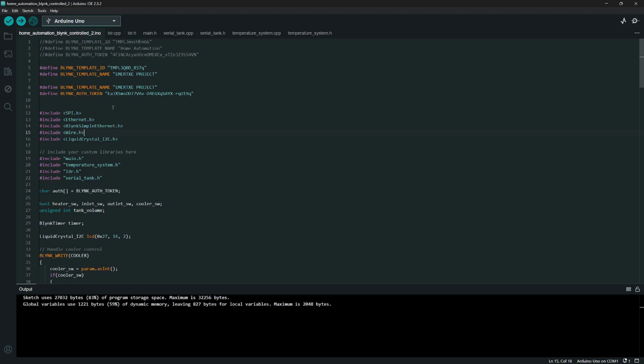Now, when we press a button, how will the sensor, or the lights as well as the inlet valves, know that we have pressed the button and wish the command to be executed? For this, we'll create a Blynk Cloud application. In that Blynk Cloud, we will configure the same virtual pins which we have selected in the Blynk phone application, and we will link both of them together.